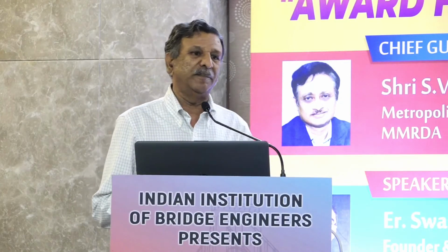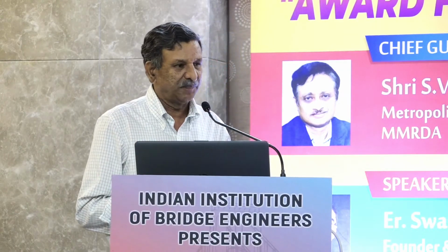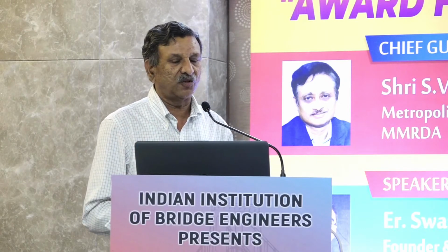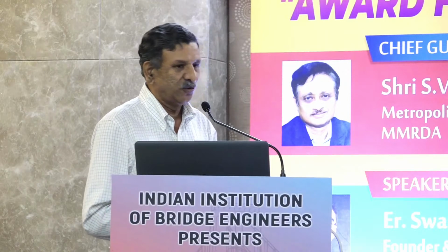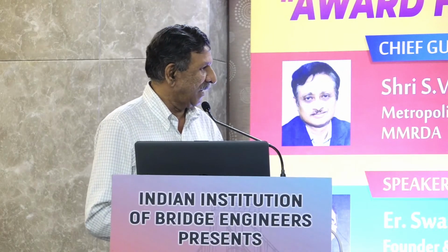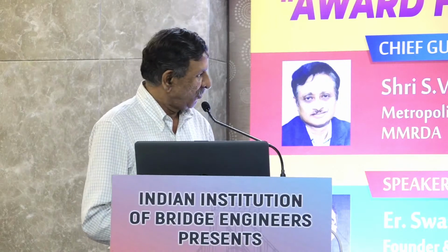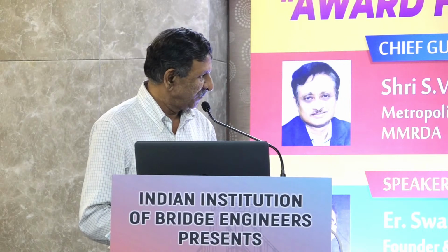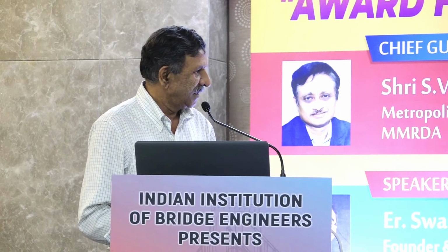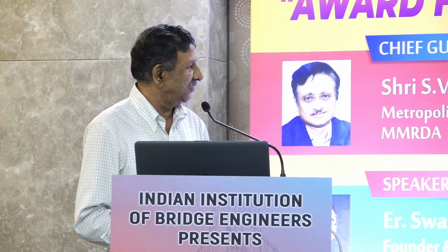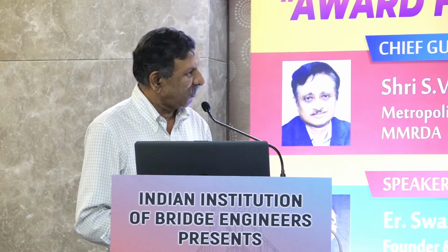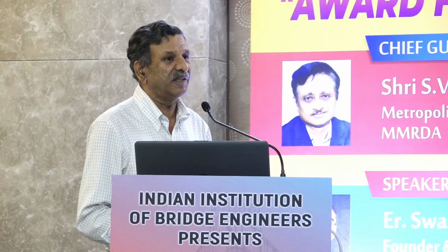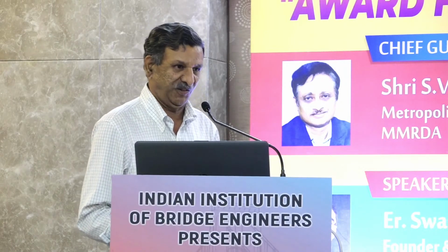I have been proud to have been associated with one iconic project, the Chenab Bridge, which we are constructing in the Himalayas. It's going to be the world's tallest bridge. Sir, to just share with you, I did make a presentation to ICE on that. 3 lakh bolts, HSFG, 32 dia, 34 dia hole, not a single hole mismatched. And the pier, which was 127 meter tall, erected at the top on a 40 meter concrete pedestal, was only off center by 27 millimeters in the transverse direction.